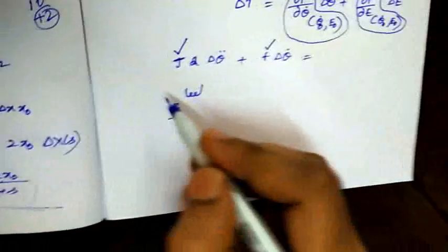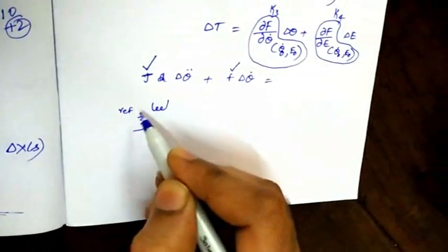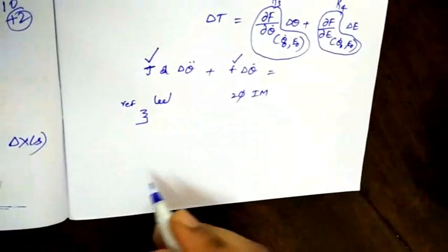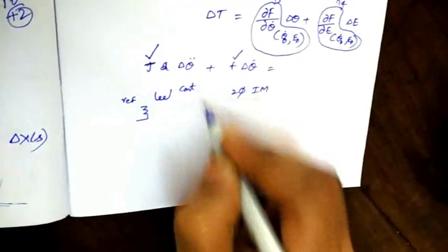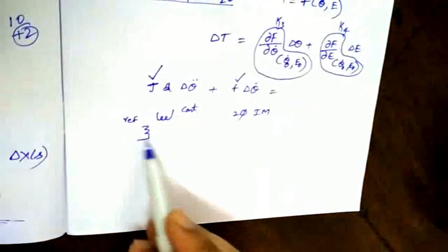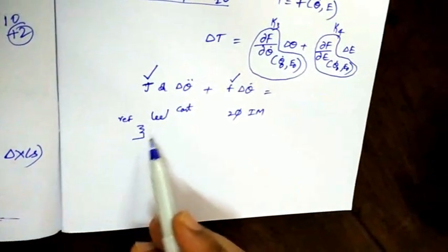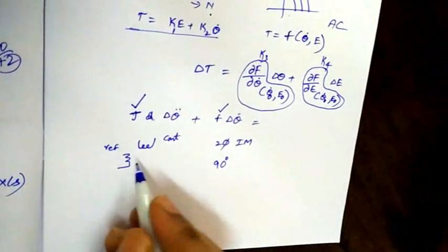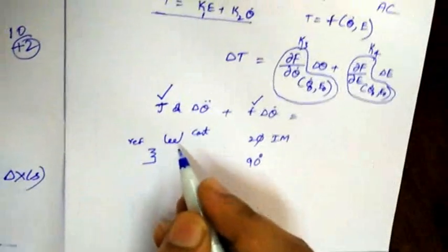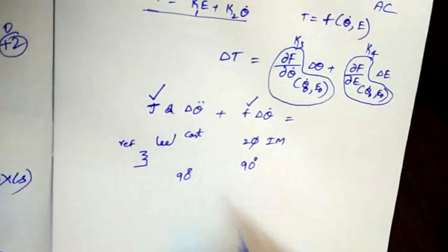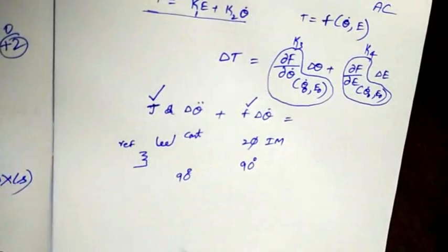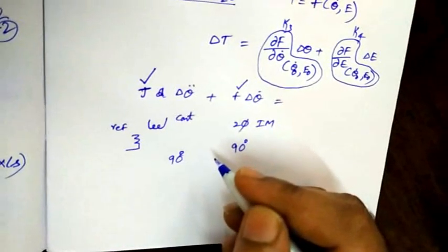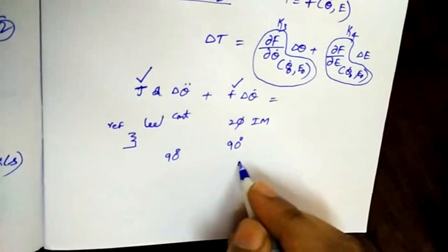Servo motor has two windings. That AC two-phase induction motor has two windings, reference and control winding. Those two windings are mechanically displaced by 90 degrees, and the power supplies applied to those windings also have a phase difference of 90 degrees. When such a condition is met, a rotating magnetic field is produced or developed in the air gap.